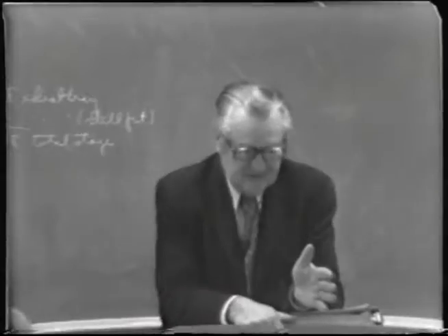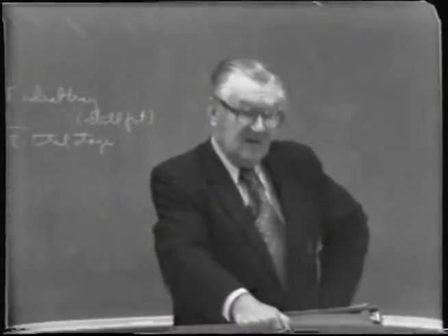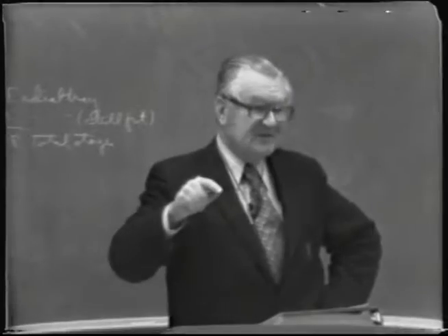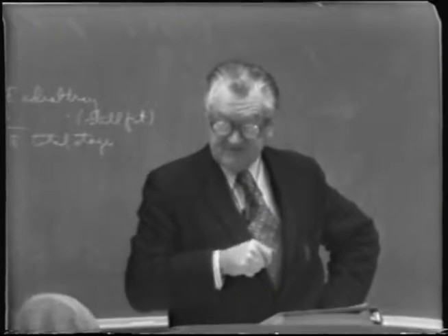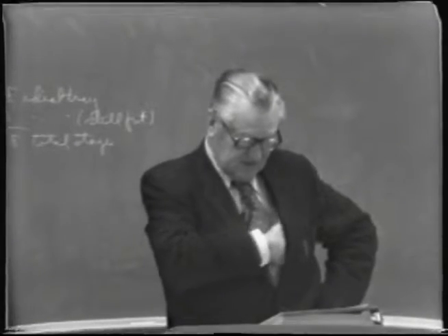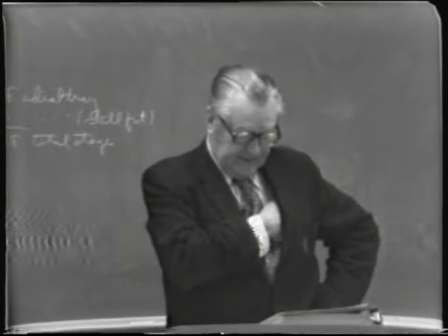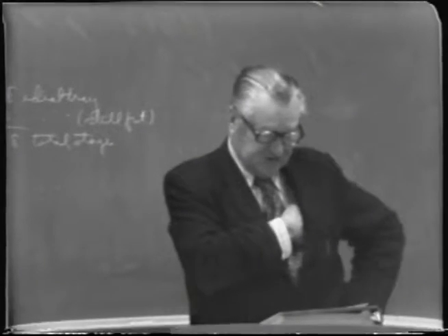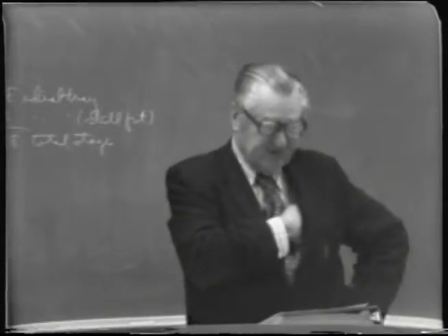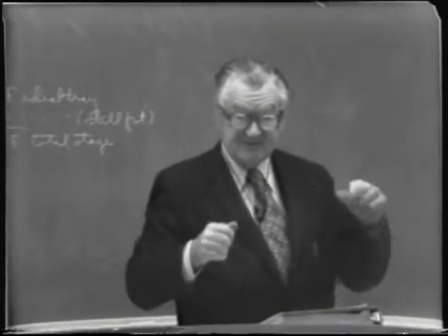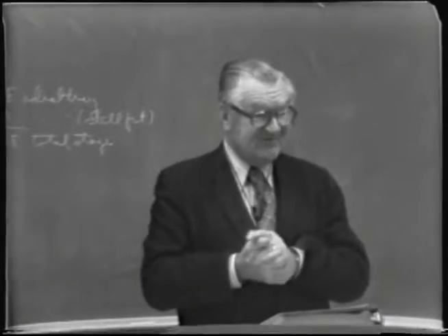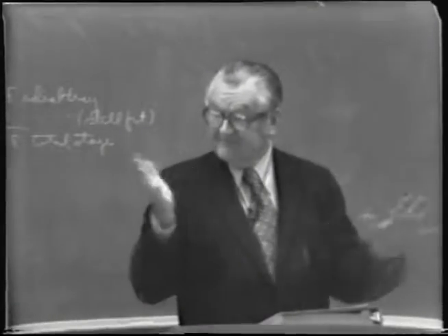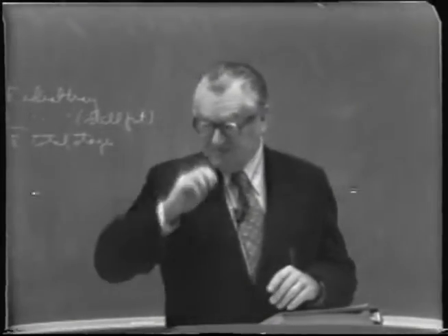Let me say that again. I want to consider the condition where the feed is being introduced onto a tray in which the liquid on that tray, or the overflow from the tray above down to that tray, is significantly different, which results in a sort of reverse action, where you're defeating the purpose of separation or concentration by mixing a stream of one composition with that of a different composition, defeating the purpose of fractional distillation, which is, of course, to separate stepwise one component from another.